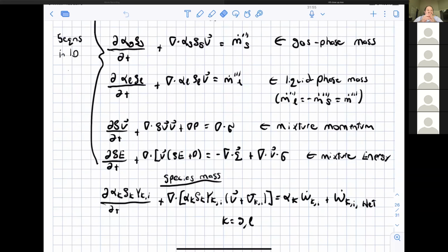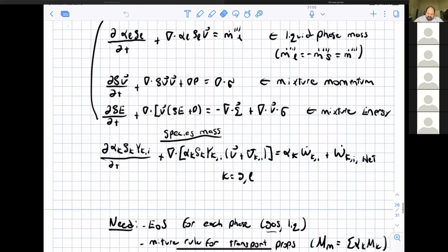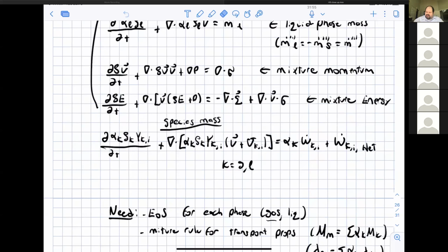And then the other alternative for multi-phase flows, if you have either a bunch of droplets or a bunch of solid particles, is what's called an Eulerian-Lagrangian approach, where you basically treat the particles or packets of particles as Lagrangian elements, and you use a bunch of techniques with that. Baer's group is a world-renowned expert at doing that stuff. But as accurate as those are, those do have some limitations.